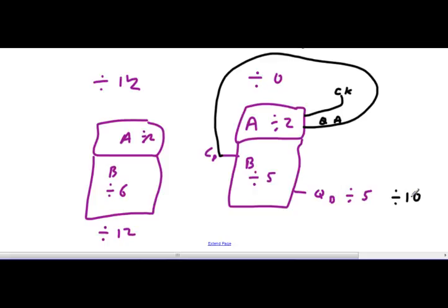Now it'll be divide by 4 at QB, a divide by 8 at QC, a divide by 12 at QD. Not going to clock pulse B, just using clock pulse A? If you only use clock pulse A, the only output you're going to have is a QA, and it's only going to be a divide by 2 counter.